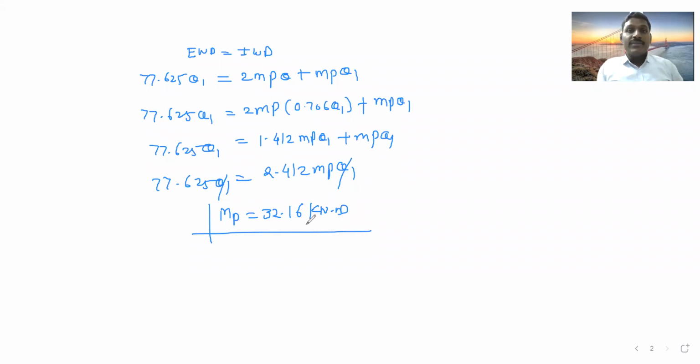Okay, so in this way we have analyzed this beam for the plastic moment. It means at the time of collapse, how much plastic moment will be developed in the particular span for AB, BC and CD. But these are the plastic moments. So what are the general bending moments for the span? We can calculate the general bending moment also.